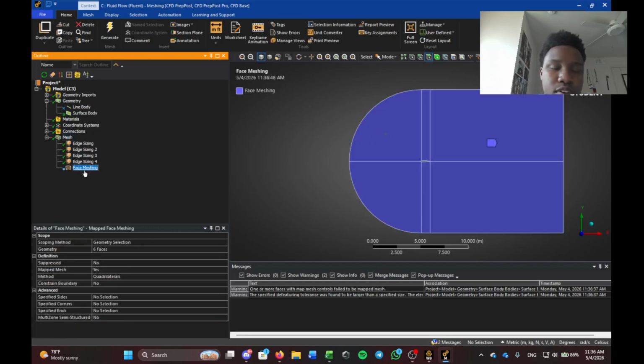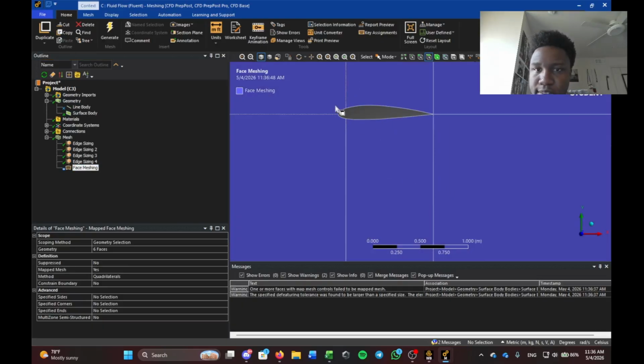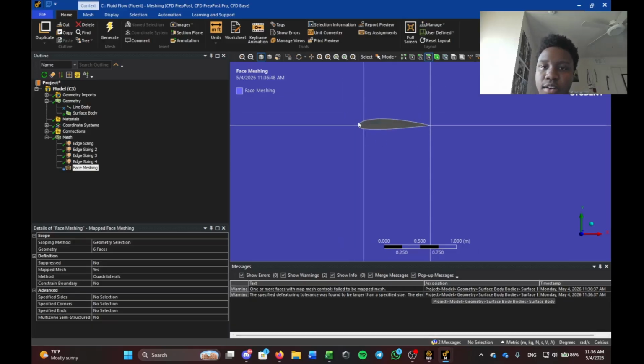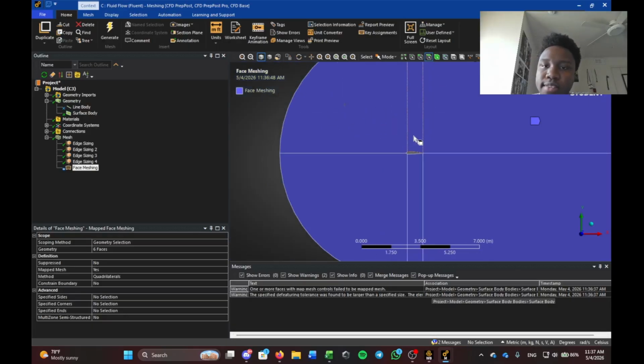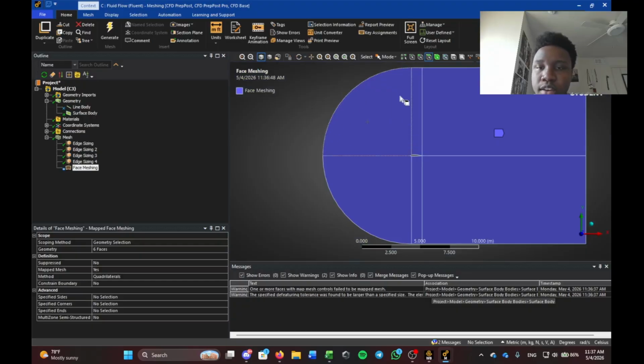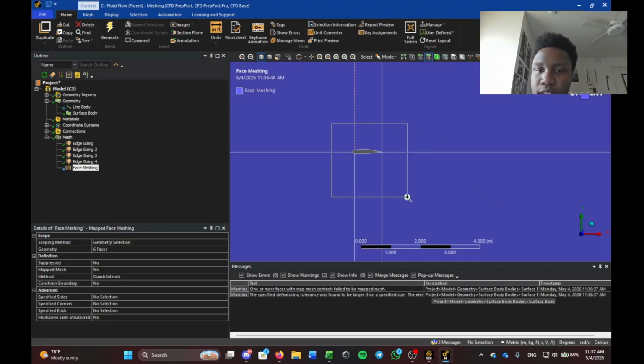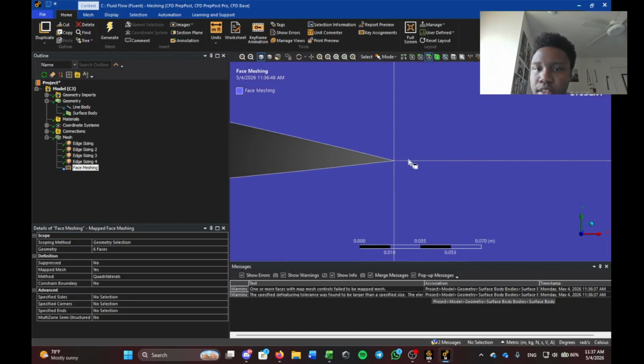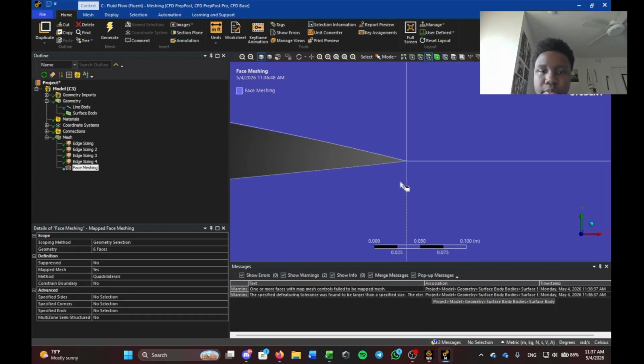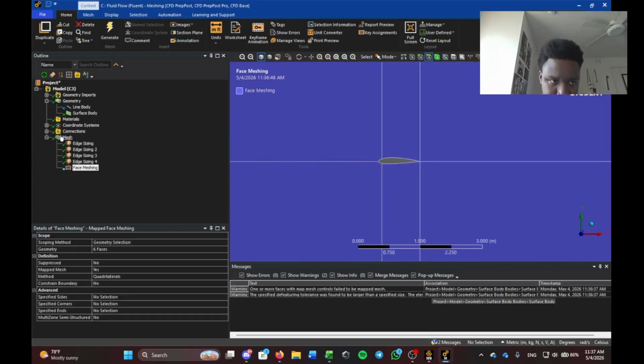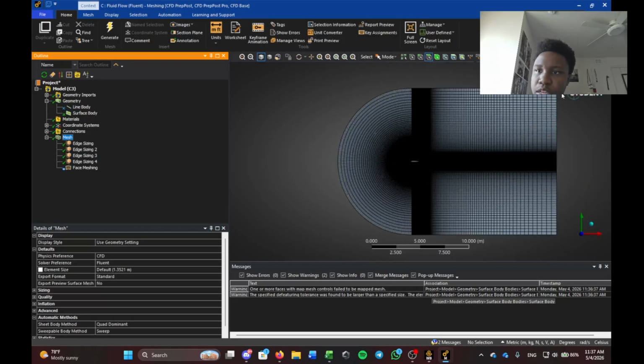I've tried messing around with uploading the airfoil using different points, moving these lines in different places, but basically that face meshing error, it's something to do with the faces. You need only 3 to 4 faces for face meshing. It's possible here it might be counting another due to the sharp edge, I'm not sure. But all I know is this is how my mesh should be looking.